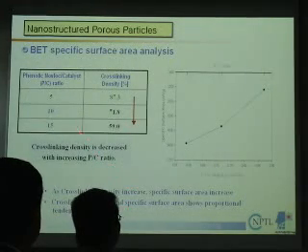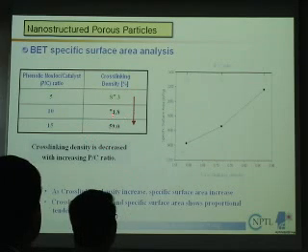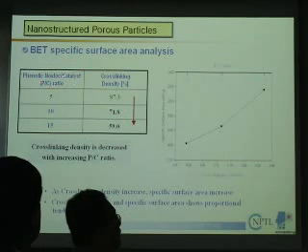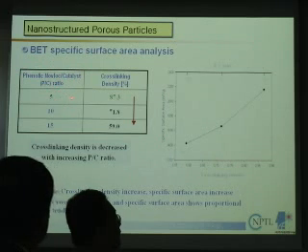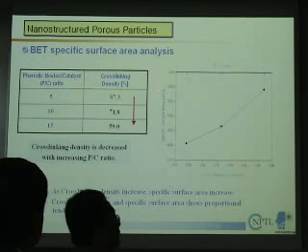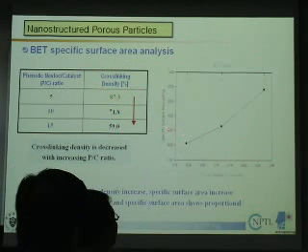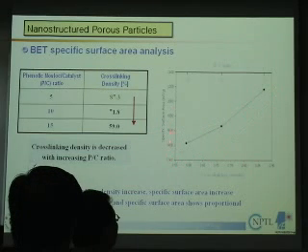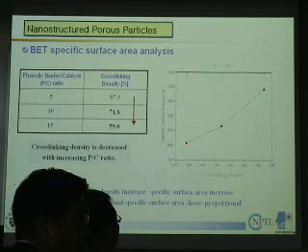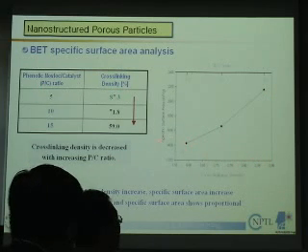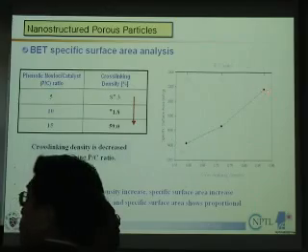And this one, yes, we did some analysis on this. Just changing the ratio of the vapor material and catalysis can change the cross-linking density. This is the main effect governing the final morphology and final surface areas. This is the total surface area as a function of the cross-linking density. As the cross-linking changes from 0.6 to 0.9, the total surface area varies from 1400 to 2400.